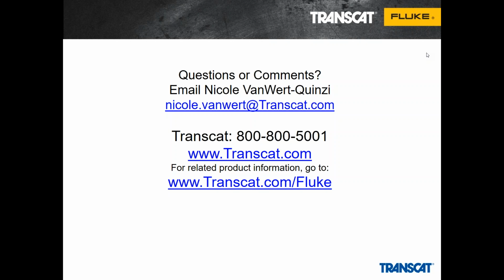Okay. How do DPCs help ensure tasks are performed as downloaded? That tends to point to that usage count that I was referring to. If the technician has gone out and performed 4 calibrations that were downloaded by the supervisor and brings them back, and the usage count and all the tasks that the supervisor wanted the user to do show as 0, the technician has gone and done the calibrations, but not using the downloaded tasks.